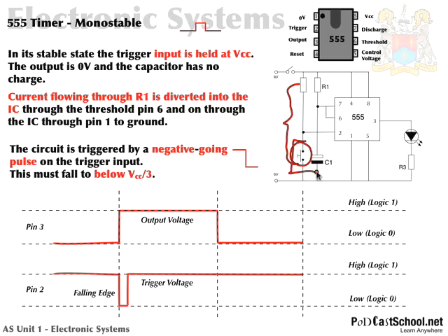So imagine a huge resistor in there, and you know that from the potential divider that the potential splits in accordance with the resistance. So big resistor, big voltage. Okay, but if that were to go very, very small, then of course 2 is basically connected to ground. Okay, so it falls, and that's what produces this negative going pulse, this bit.